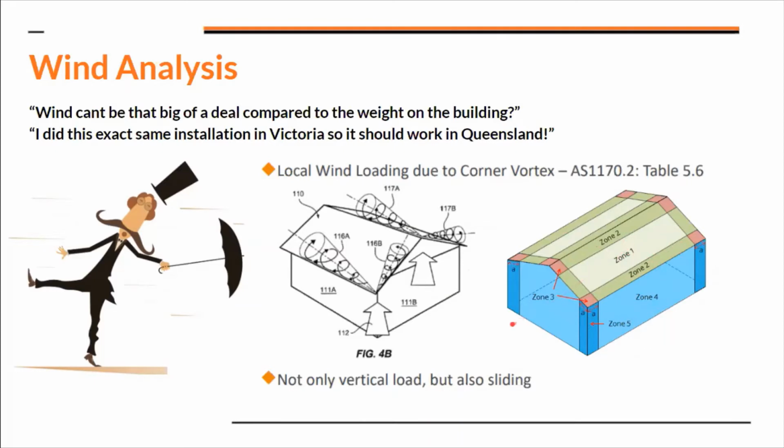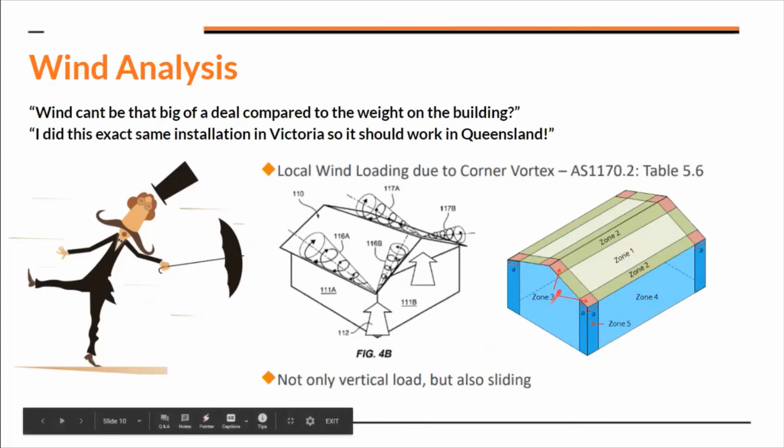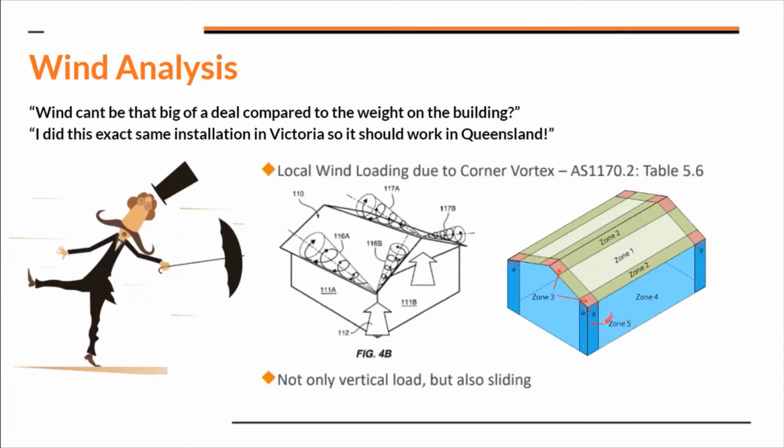In the same case, you have the same thing on zone 3. The wind wants to go up. Now you see this corner is being affected by two-directional wind, and that's why this corner usually has a much higher pressure than the internal zone. That's why you see in some of our certificates that these corner areas are marked out as needing additional rails, or they might be excluded altogether. So understanding that is where this comes from. We'll go into a bit more on what the shapes look like in the next slide, but it is a very important component.